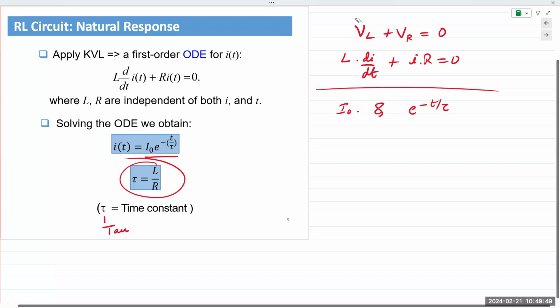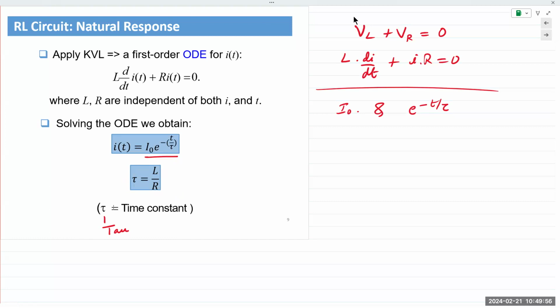So let's take a look at the equation. What do we have? We have I0, right? I0 is the max value. So if you plot this at time t equal to 0, meaning when we began our analysis, the value of the inductor current I of t would be right here. I0, the max value. And from that point, it's all downhill. It's discharging, so it's losing all of its energy, except it's not linear. It always follows an exponential form.